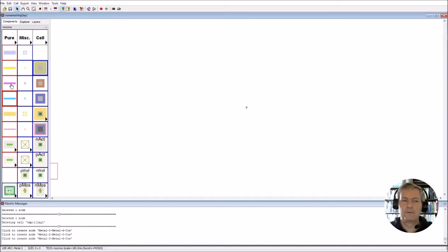And then on top of that, we would have the next metal layer, which would be our metal 2. On top of that we would have an oxide or insulating layer, and we'd have our metal 3, oxide insulating layer, then metal 4. So we're going to have this sandwich structure between these metal layers. The reason we're having these metal layers is that it makes the routing of our devices a lot simpler. If, for example, you've got hundreds of millions of transistors and you want to connect them together, the routing is really going to be very difficult. So you want to have as many of these metal layers as you can in order to make the routing simpler. We'll get into that in a minute anyway.